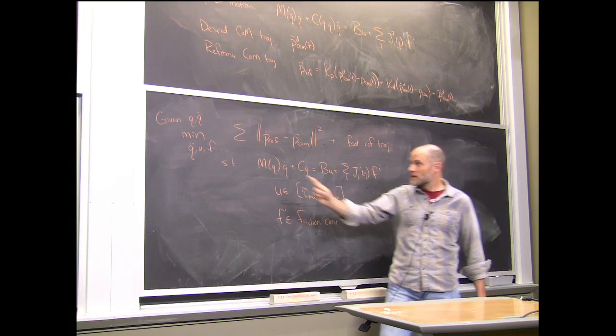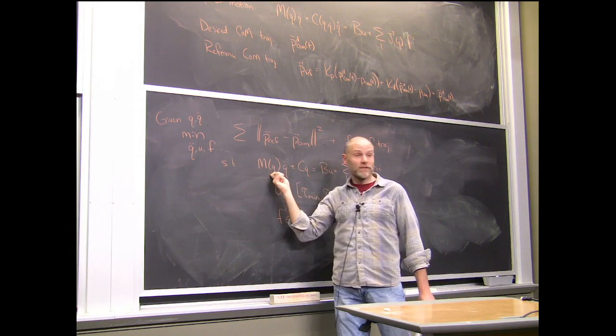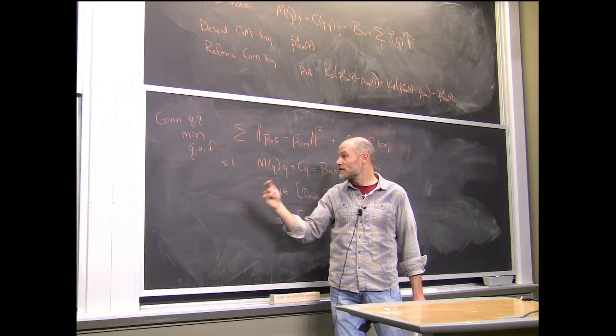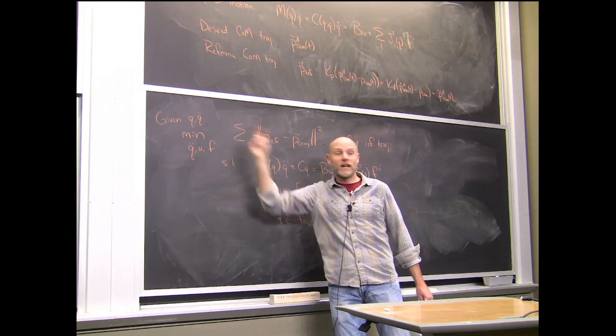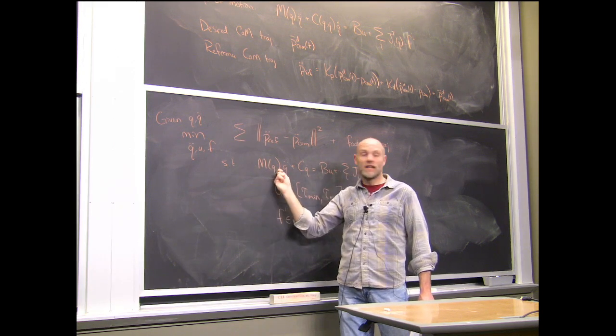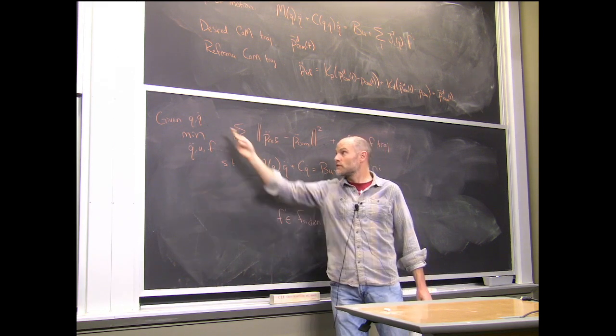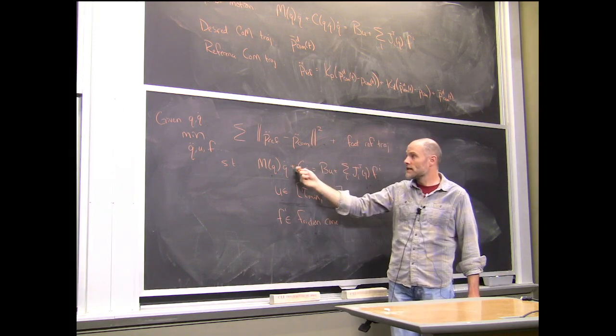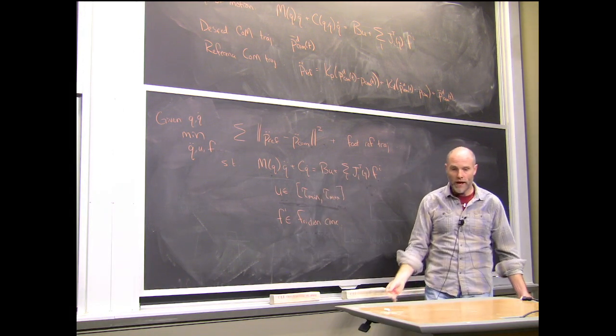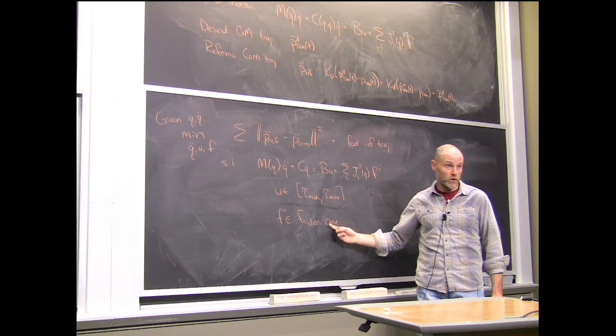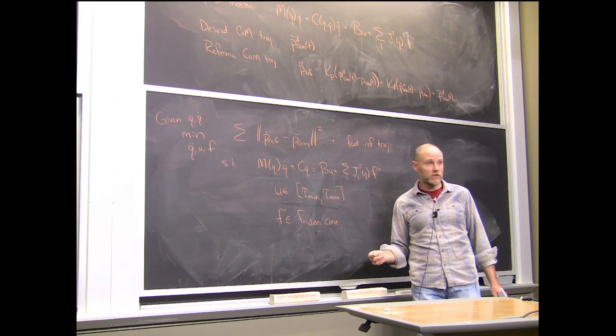The big reason is because Q and Q dot are given. As soon as I look into the future, Q and Q dot are going to be a function of my first decisions, and then the nonlinearity creeps in. But for one step, everything's beautiful and linear. And this runs at high rates on the real robot, and that's what's doing the balancing control.